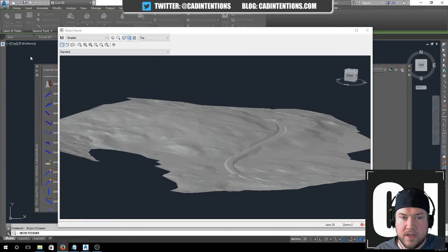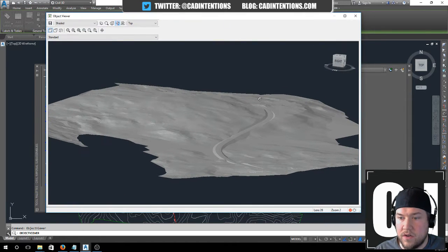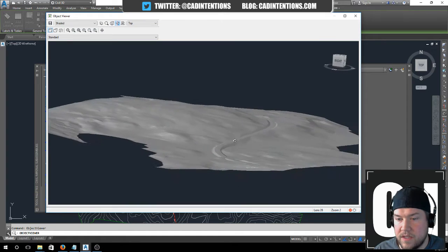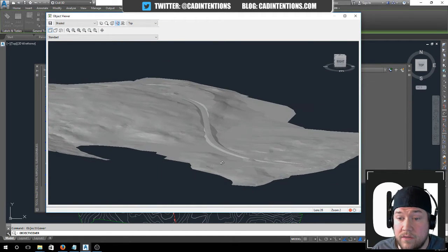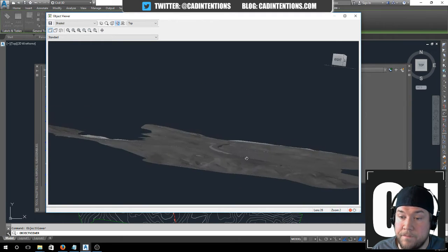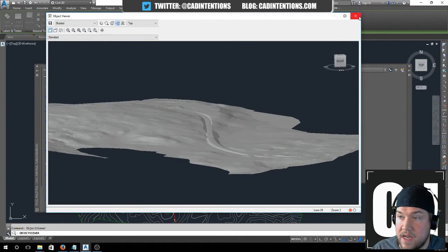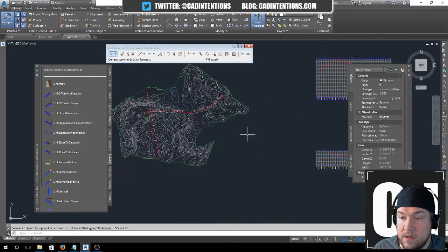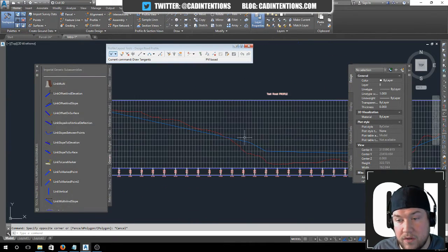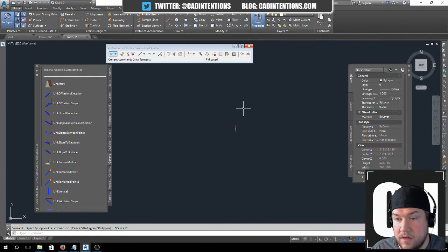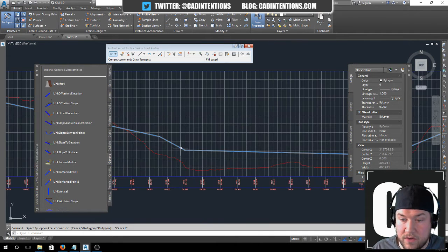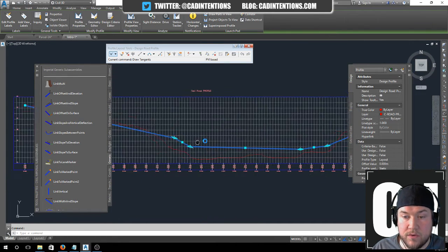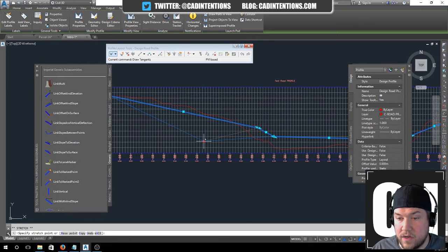Yeah, if you're just joining us, we've just gone over a quick way to design a road in Civil 3D, as well as how to cut a profile or a section from an existing ground surface. And I'm just showing now how dynamic the roads, or corridors, are once you get them built. So once we've done all the setup, like building our assembly here and our design profile, you can change them on the fly and have your road adjust accordingly.